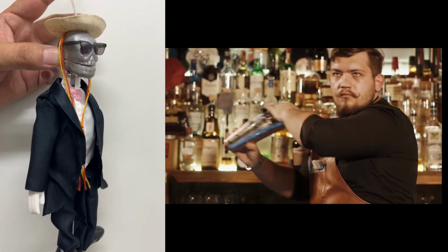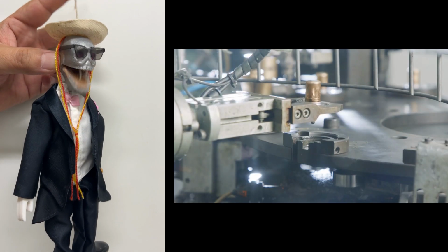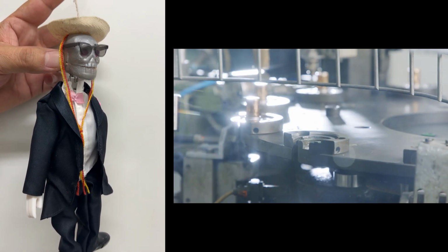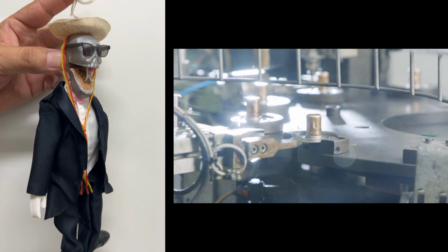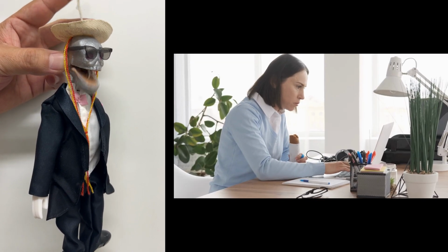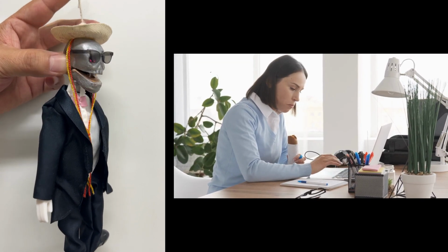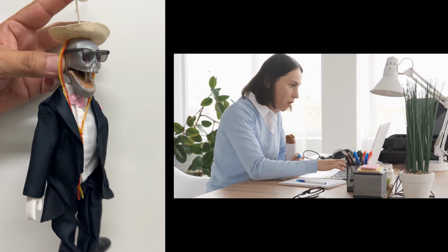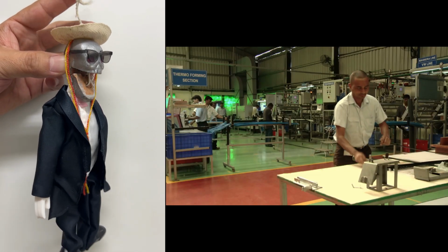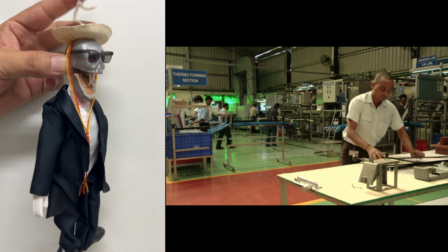But before that, here are my final thoughts. Fishbone diagrams are great tools to find out the root cause of a problem or condition. But be careful. Never try to create a fishbone in the comfort of your office. No, no, no. You need to perform a real shop floor investigation before creating the diagram.